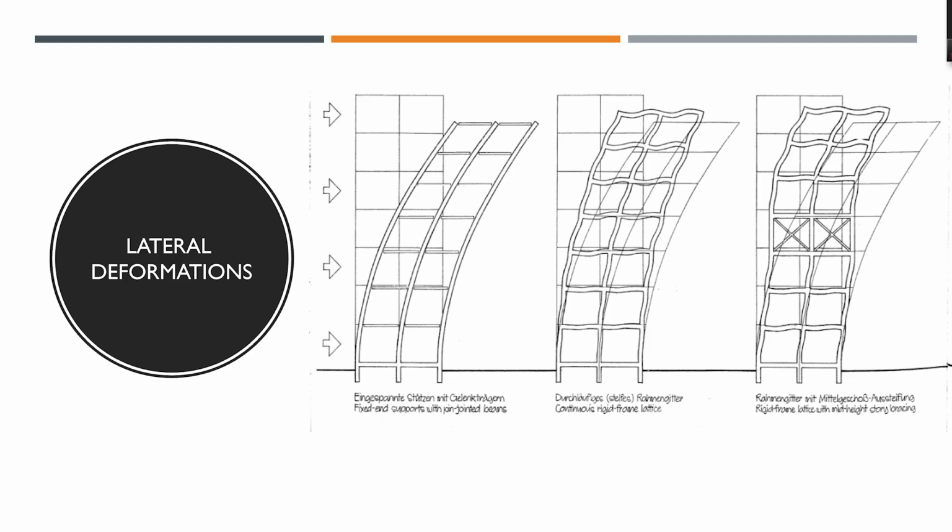If you have a beam and column of similar size, it will be like this. Beams will deform, columns will also deform. This way you can see columns are not deforming. Columns are just bending like a cantilever. Each column is bending independently because the slab is not stiff enough to force the column to rotate. It's only connected in a small place. If you have a beam, the beam will force the column to rotate, and each floor will have local deformation of the column. Stiffness will increase. And then if you put in a bracing, that floor will become almost rigid. It will not deform, so the total deformation will be reduced.